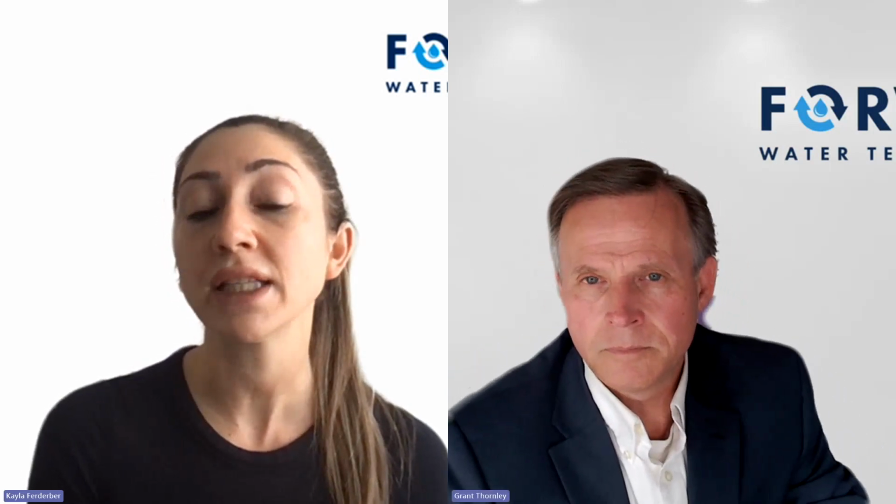The heart of a direct lithium extraction process is the sorbent used in recovery of lithium from brine. Sorbents with base materials of aluminum, magnesium, or titanium are the most common sorbents used in DLE applications today. However, simply selecting one of these sorbents does not guarantee good lithium recovery if the process used is not optimized for its operation. In our webinar series, we examine and discuss the use of lithium aluminate layered double hydroxide chloride sorbents, contaminants of concern, and how to maximize lithium recovery by optimizing process operations.